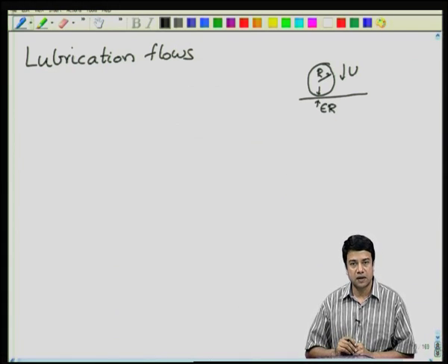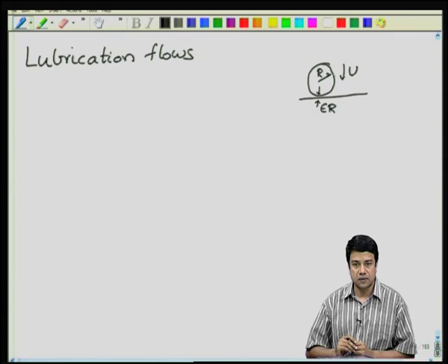As I said, we will analyze this in the Stokes flow regime. That means that the force at an instant in time is determined only by the positions and velocities of all the surfaces at that instant in time. Recall, Stokes flow equations are quasi-steady. Therefore, there is no time dependence within the equations. So, given a configuration, particle coming towards a surface with specified distances, I can calculate the force without knowing what the history of the system was in time. Okay. So, this is all I need in order to calculate the force: the velocity of the particle and the configuration.